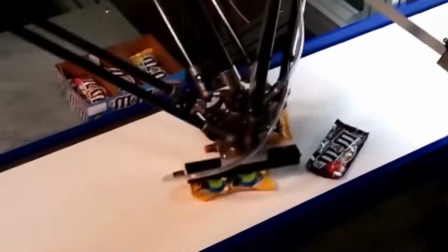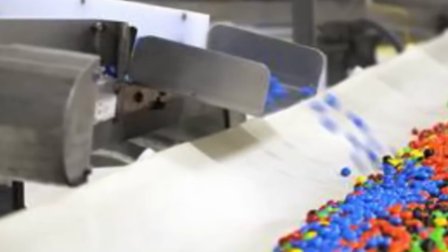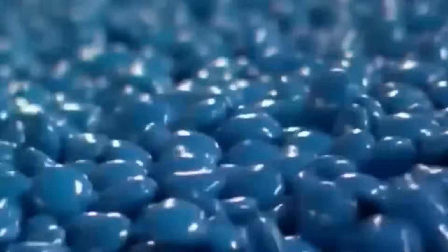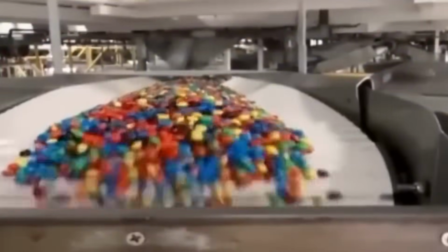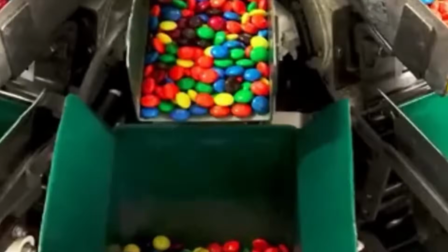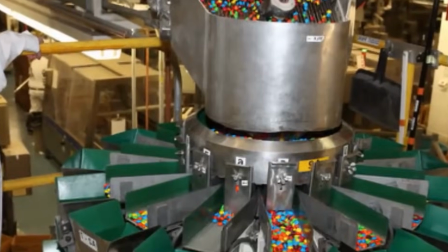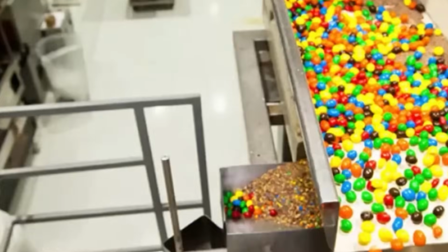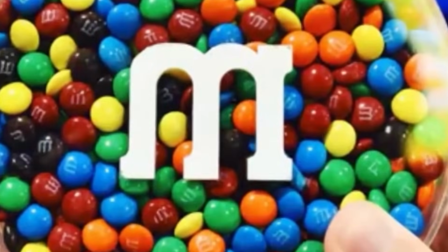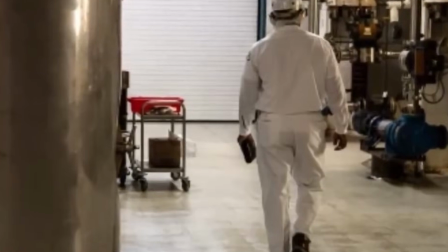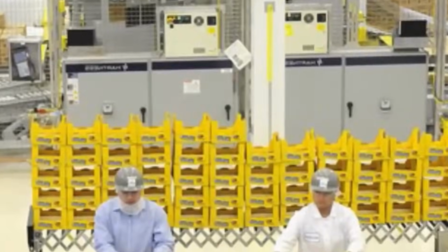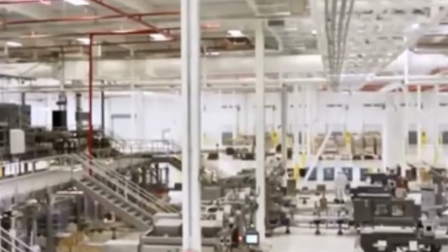Accepted product is conveyed to the packaging system, where candies are temporarily stored in surge hoppers with level sensors to buffer production flow. Product is dosed using multi-head combination weighers that calculate the optimal combination of candies to achieve target package weights, typically 34 to 80 grams, depending on SKU. Weigher buckets are constructed of low-friction stainless steel and cleaned regularly to prevent flavor carryover or build-up. Filled product drops into vertical form-fill seal machines, where printed laminate film is formed into a pouch, filled, and sealed with constant heat seal bars.